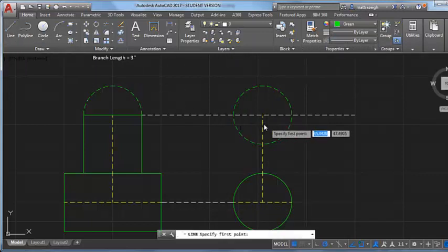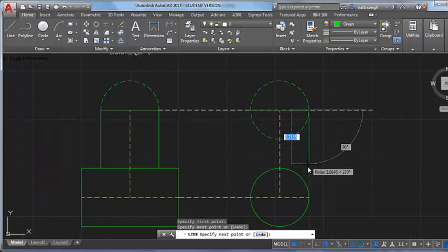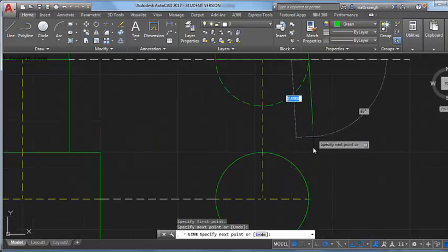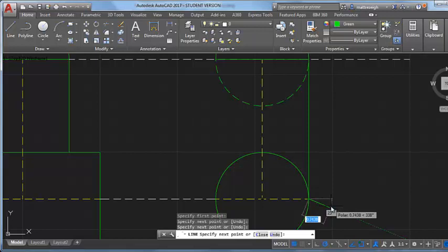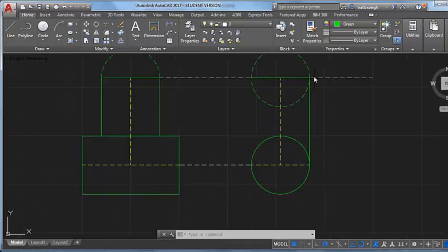So I'm just going to use my lines here. This is a solid line. That's the top of the branch. And see, when I bring this down, this is where it starts to give me that information I'm looking for. This comes down until it meets the center line. And that would essentially be where that branch would terminate, because if it went any further than that, it would come up off the header. So when things are diameters, they terminate at center lines there.